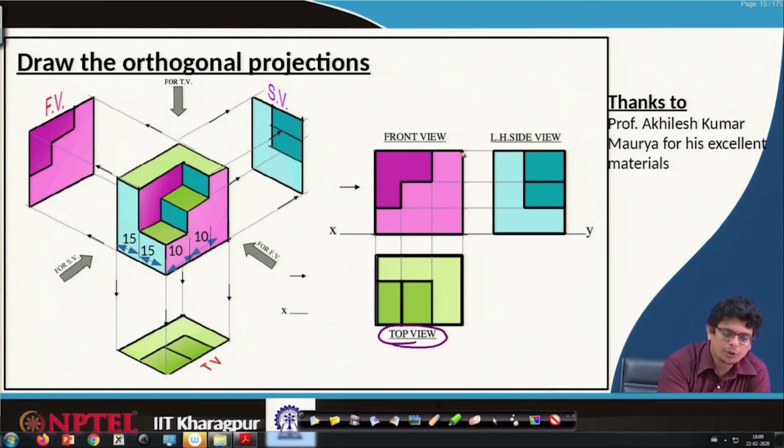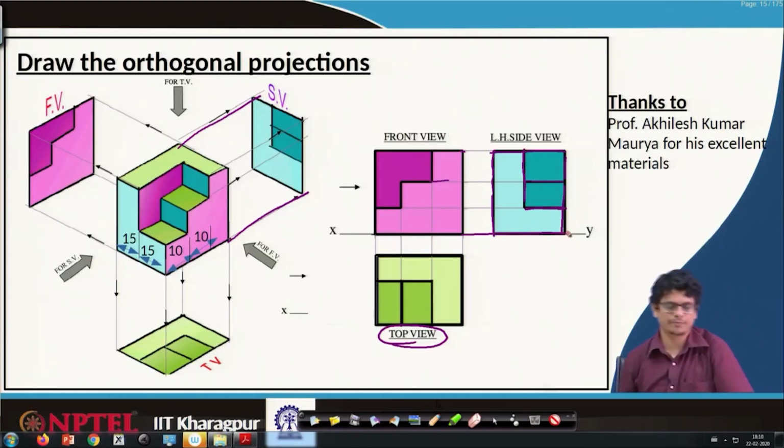Once that is done, project lines in this direction to construct, because this is the line what we are going to project. Again leave minimum 4 to 20 mm kind of gap, make a square of 30 mm by 30 mm, project these lines, construct this one. So, after projection we will have this picture.